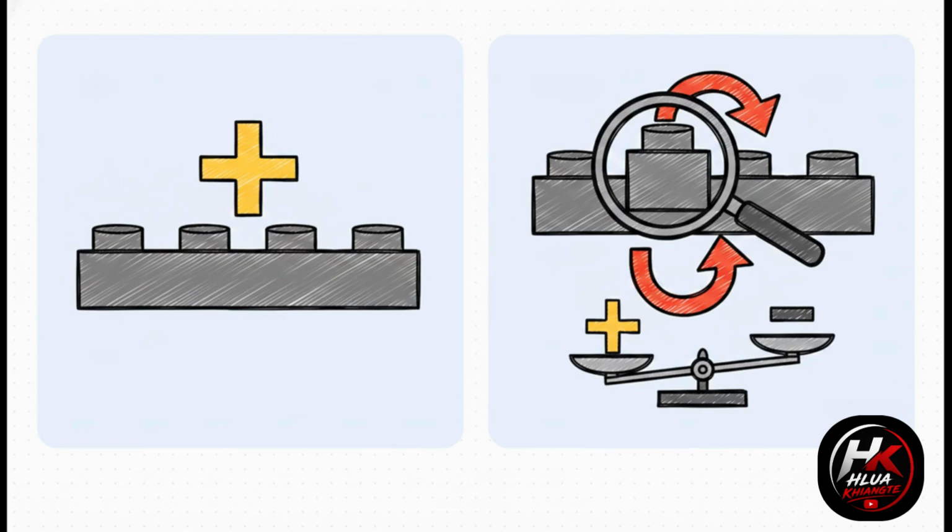But think about this. How does a computer understand negative numbers without a physical minus sign? Engineers use a brilliant trick called 2's complement for signed numbers. The bit on the far left acts as a sign indicator. To make a -5, the computer takes a +5, mathematically inverts all the bits, and just adds 1. It's such an elegant hardware workaround because it allows the chip to process subtraction exactly like it processes addition.